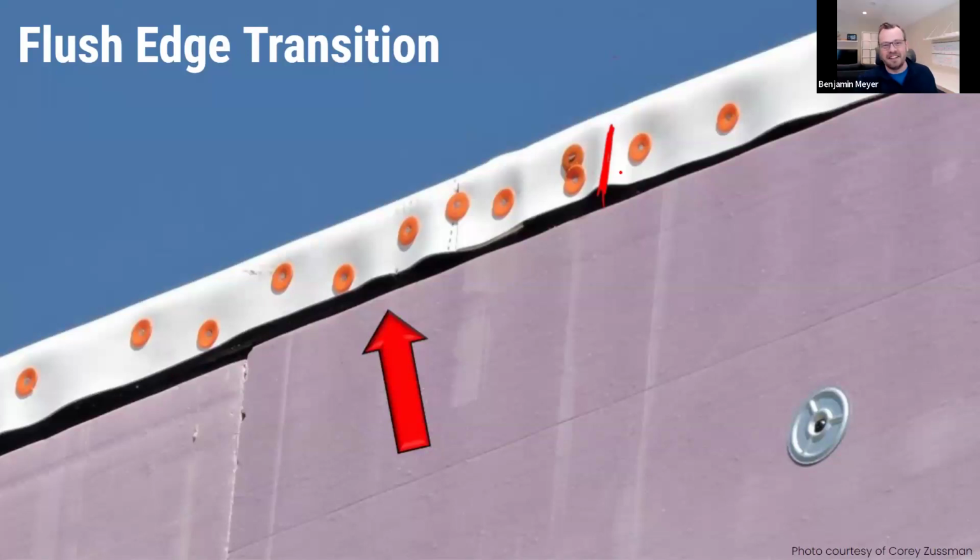That's right. And so again, it's about, are the materials able to do what we're asking? It's easy to draw a dashed line and say turn roof membrane here, and I've seen some actually turn back and go along behind the blocking. That's the design intent. When it comes to the field, like, you know, 1 turn is kind of the limit on this material.